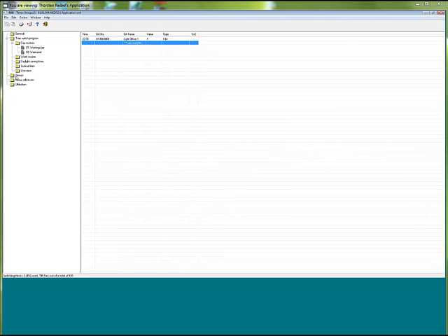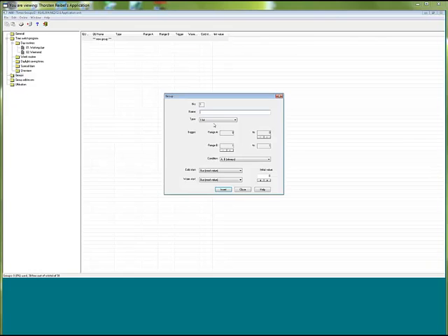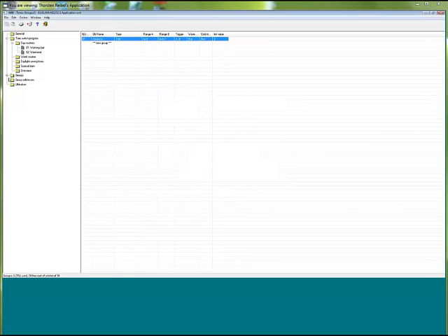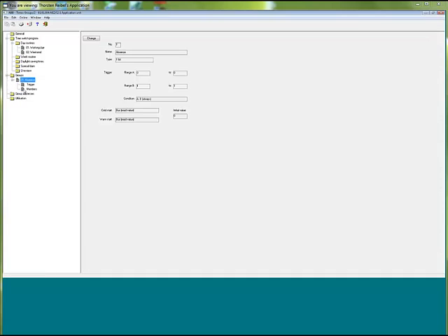Good. Finally, I would like to go to the group function. Remember, a group is a collection of group addresses sent out more or less at the same time, triggered by another group address. We have to create a new group. Let's call it absence, for example. Absence is the name of the first group I create. I insert this, and then you will see here our first group with a trigger and member.